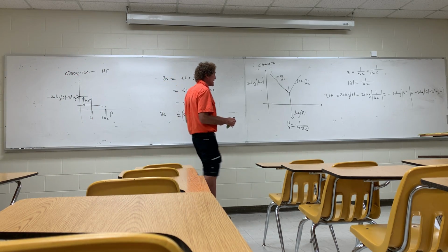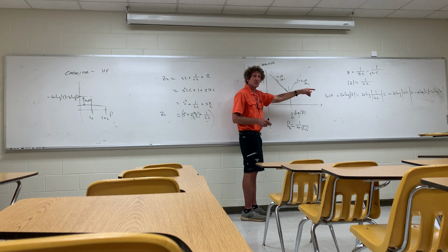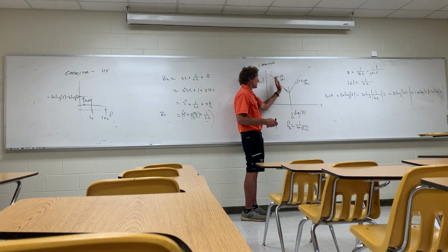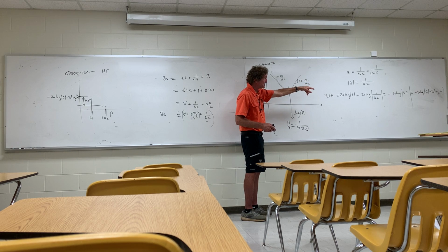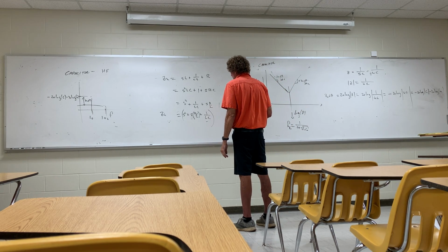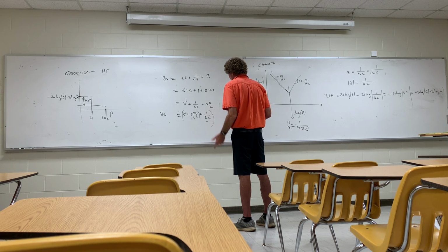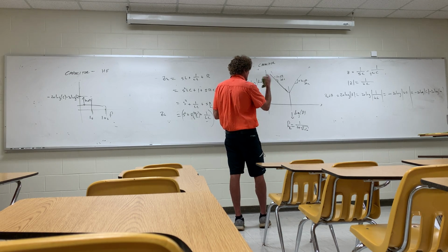These are 20 dB per decade because early on a capacitor looks like a capacitor. I just showed you it falls off as 20 dB per decade. Once it hits resonance, then it starts going up at 20 dB per decade because there's an S squared that's interacting with a 1 over S term, and effectively it means it's going up as S. And if you actually look at the impedance, this is sort of self-fulfilling, but that's what it will look like.